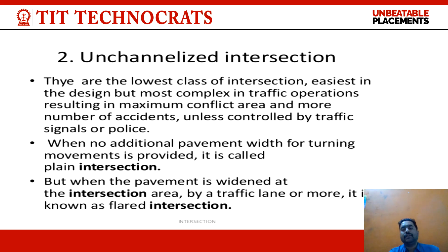What do you mean by unchannelized intersection? They are the lowest class of intersection, easiest in design, but most complex in traffic operation, resulting in maximum conflict area and more accidents, unless controlled by traffic signals or police. When no additional pavement width for turning movement is provided, it is called a plain intersection. But when the pavement is widened at the intersection area by a traffic lane or more, it is known as a flared intersection.